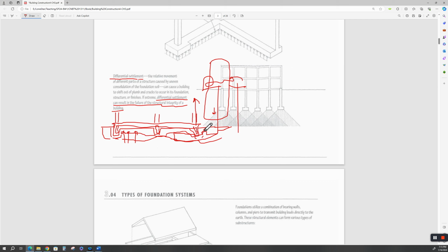So if you're going to design a house near a tree, you need to get with a good tree expert and find out where those roots are. Dig a trench, cut those minor roots, and put a root wall in between the house slab and the tree. And then put irrigation out here so that you can water it with good old H2O.